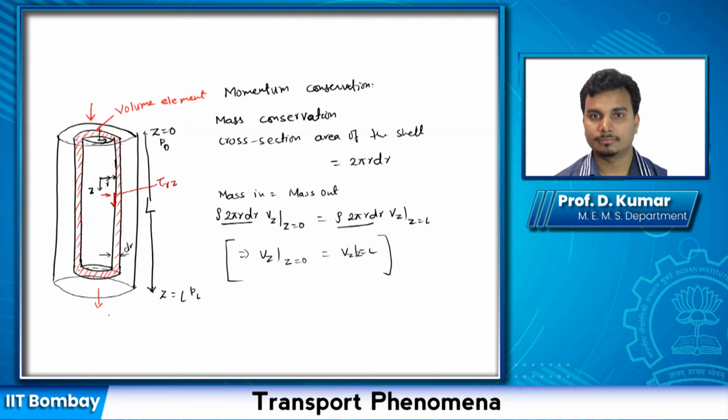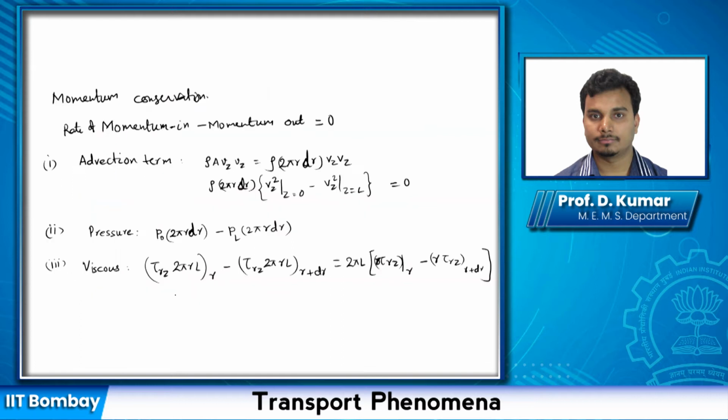Yeah, of course. We will have gravity, right? So gravity will help this flow. It's acting in plus Z direction. So what we can write, gravity will be just m times g. So m is your density times volume; it's incompressible, so that is fine.